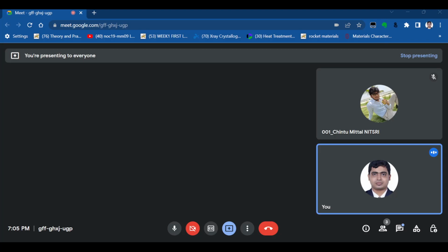Okay, so this one is our final Mohr circle. So as per the question, the principal stresses are 250, 50, and minus 50 MPa. So this one is our 250, this one is 50, this one is minus 50.